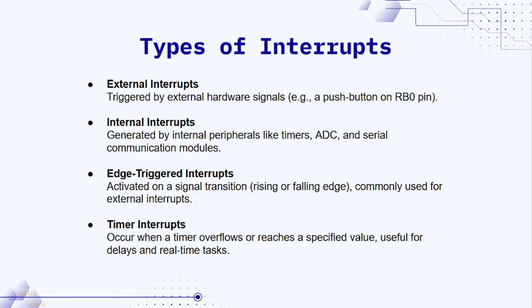Interrupts are basically a kind of program. ISR is a kind of program which is called interrupt service routine. So what happens when an interrupt occurs is the microcontroller stores the address of the main execution, jumps onto the ISR, performs the ISR, then returns back to the main execution.